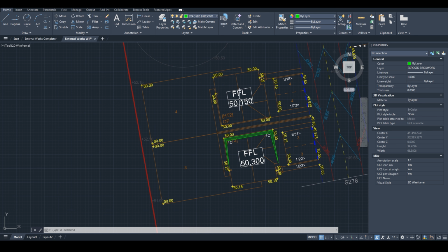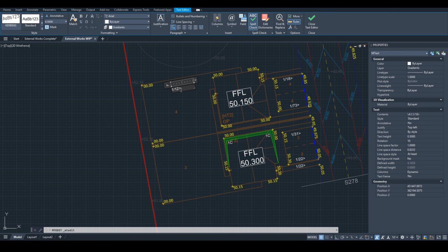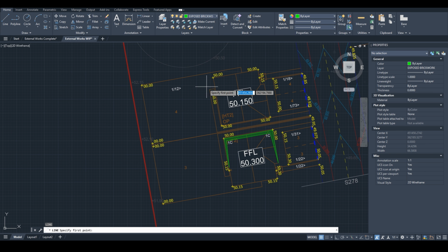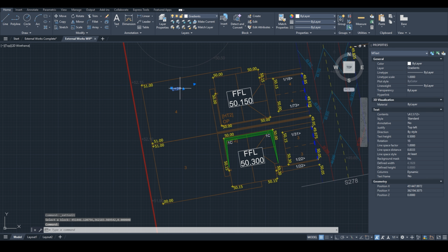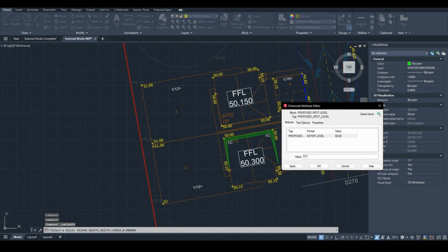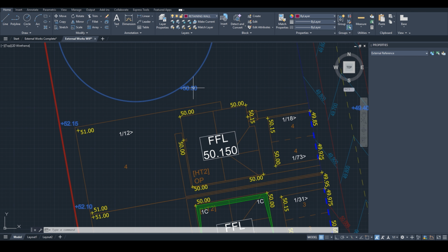The garden boundaries will typically be constrained by either being bounded by another plot's garden or the site boundaries, such as in this example. We are going to want to tie our levels into the existing levels at the boundary. However, you can see here, the existing boundary level in grey is quite significantly higher than our levels at the plot. For this reason, I am going to slope the garden as steep as the developer is willing to go to get as close to the boundary level as possible. I am using 1 in 12 as the maximum garden gradient here. I also want to keep the levels either side of neighbouring garden fences the same level where possible, to prevent requiring additional retaining. You can see that the proposed levels still do not tie into the existing boundary levels.